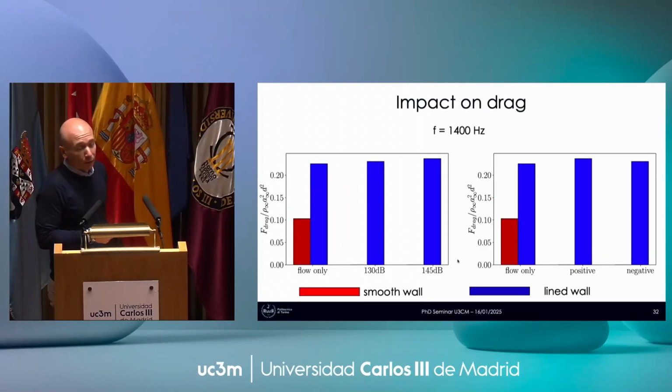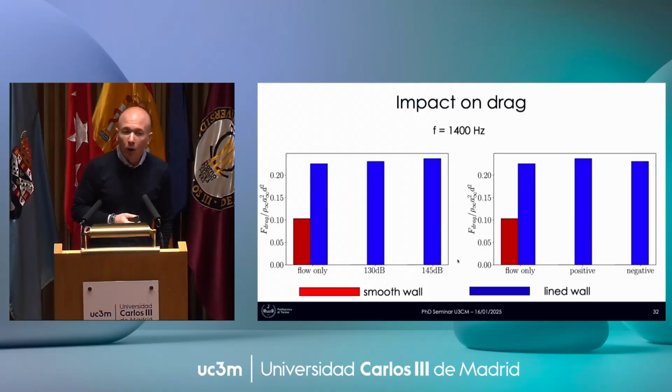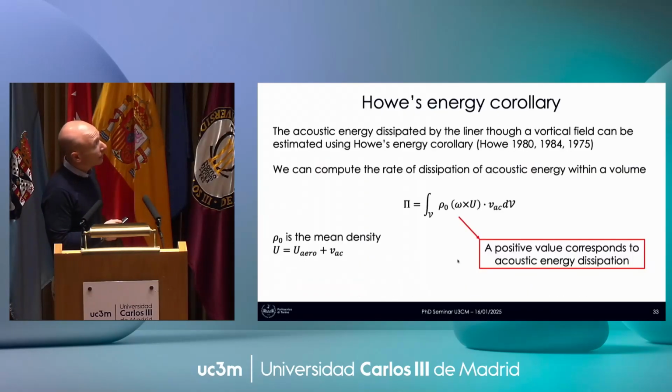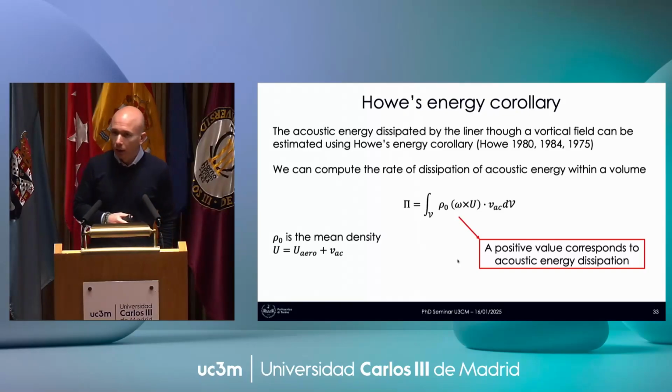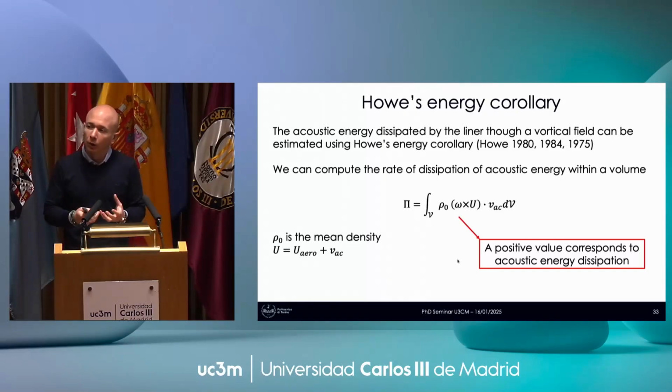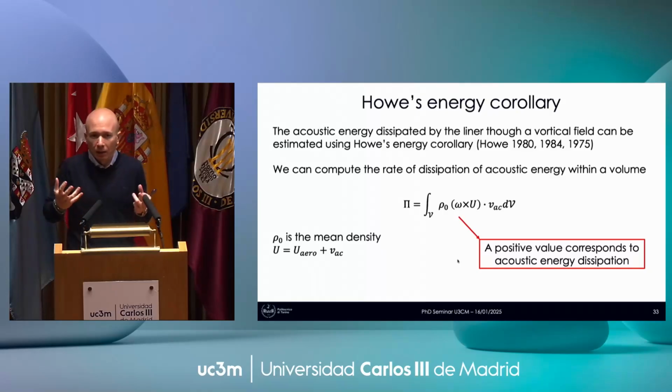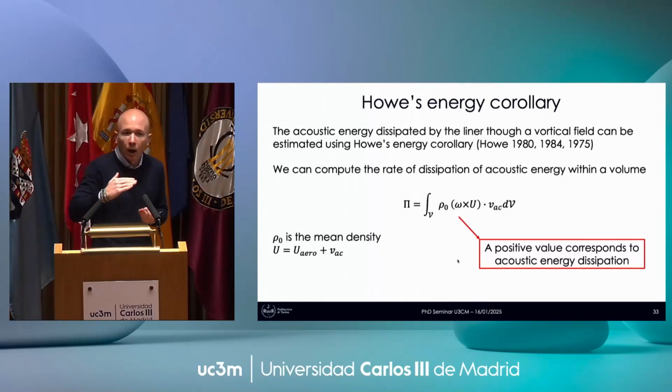And of course, this has an effect on drag. So our goal now is to understand how to reduce drag by also minimizing the interaction between the acoustic source and the flow. The last thing I want to show you is, so the first thing we understood is that, okay, I have a vortex. This vortex is somewhat blocking the acoustics. Then it's changing a bit the shape of my original orifice. This is one of the reasons why my resistance goes up. I have a smaller orifice.